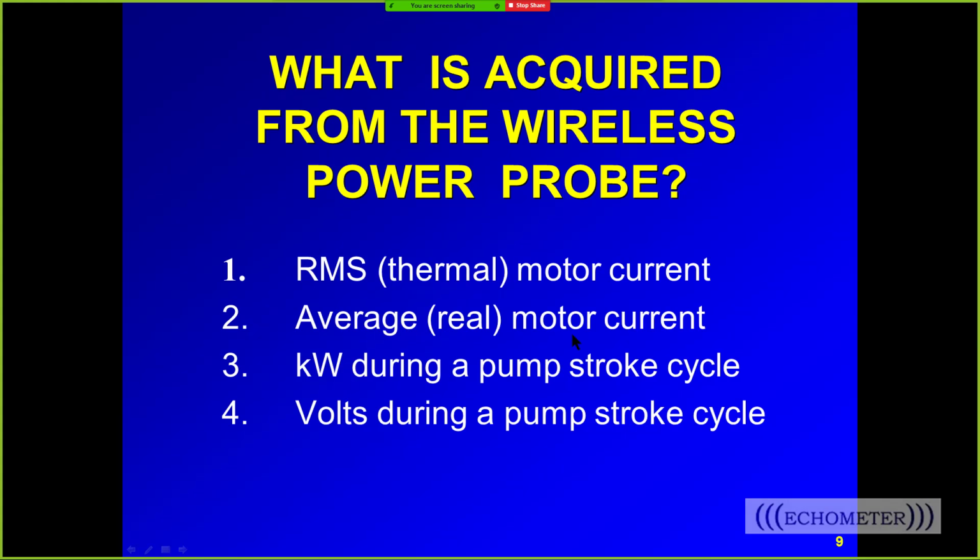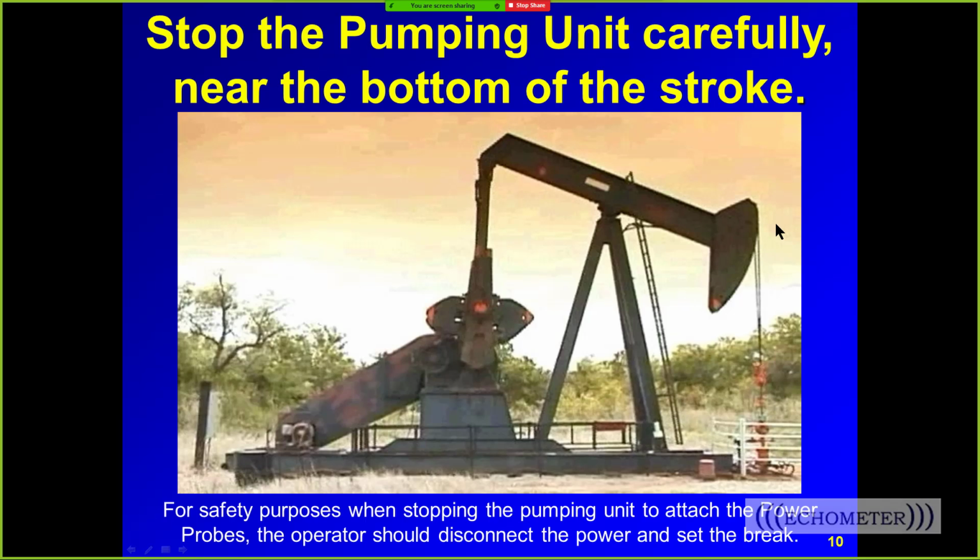I like the relationship between the kW and the net torque. I like knowing the input power and the efficiency of the system. We've added the voltage to come up with the line losses. All those are important too. You can't really save power in your company, minimize your power bill, if you don't know where your power losses are. And that's the advantage of the power probe, is to know where your power losses are.